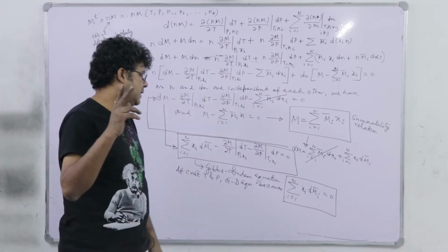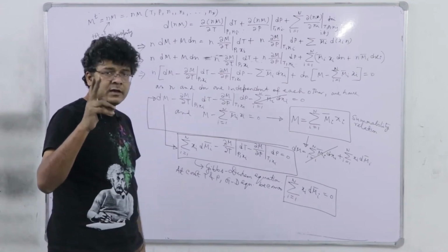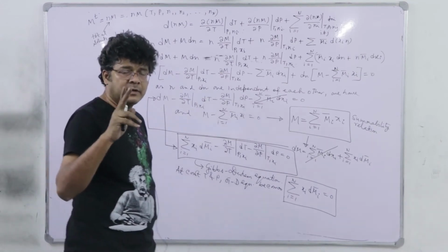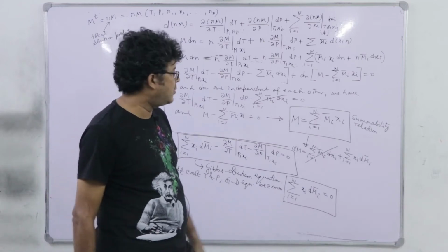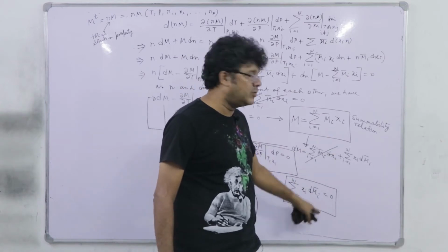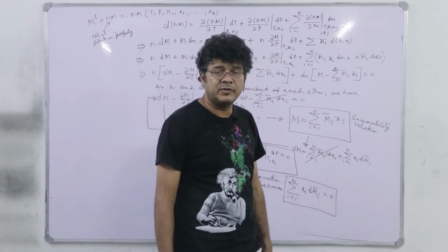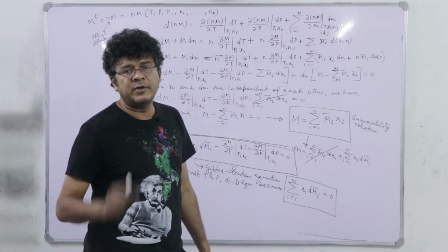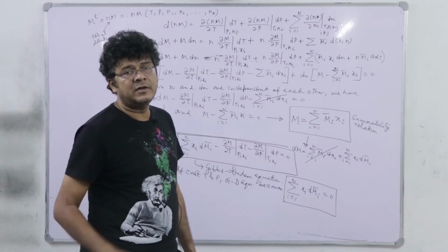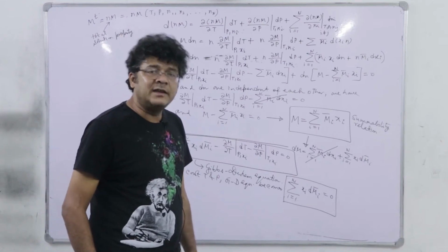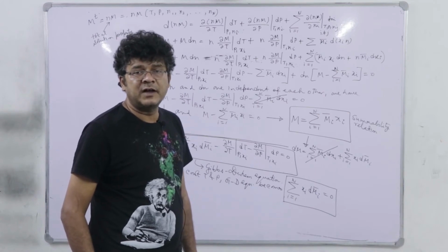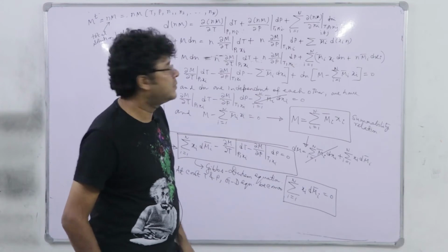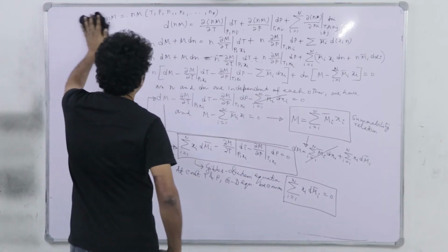we have only, when we think about the degrees of freedom in a binary solution, we have M1 bar and M2 bar. These two are the partial molar properties, and we have two equations. One is summability, another is Gibbs Duhem at constant temperature and pressure. We consider constant temperature and pressure equation for simplicity, right? So, for a binary system, we can express M1 bar and M2 bar as an explicit functional relation with M and X1.